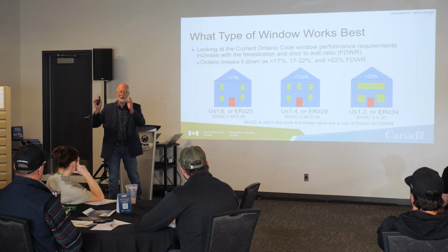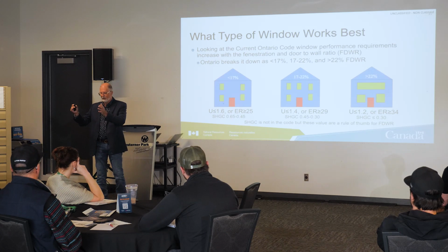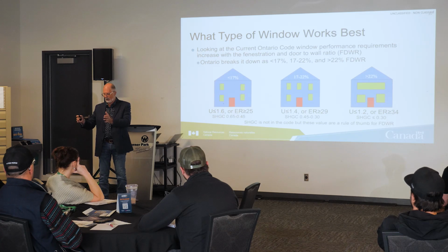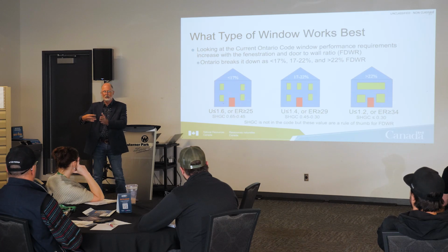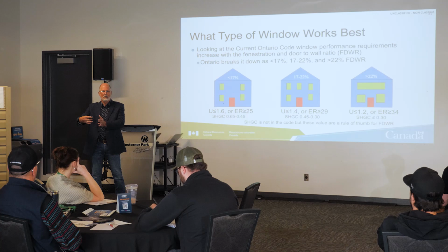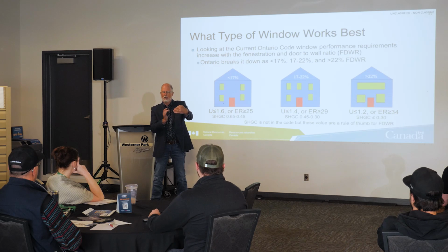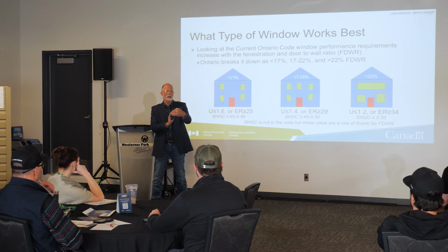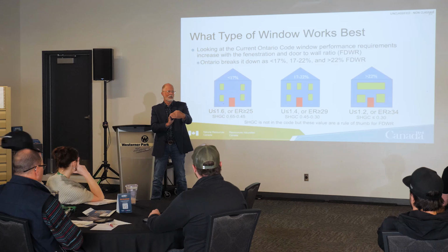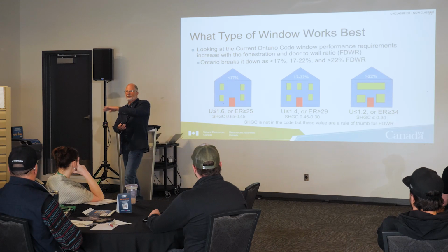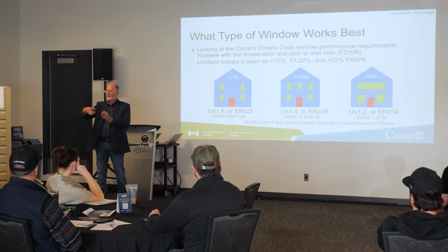Give you an example. We did an energy model, or I used to do an energy model, of this one particular model a builder had. It was designed to sit on a corner lot. And when it sat on the corner lot, on this corner, there was so much window there that it was 25% better than code. And then when they put it on the opposite side of the street, it was in the shade, it was 10% below code. Just from the windows, solar heat gain.